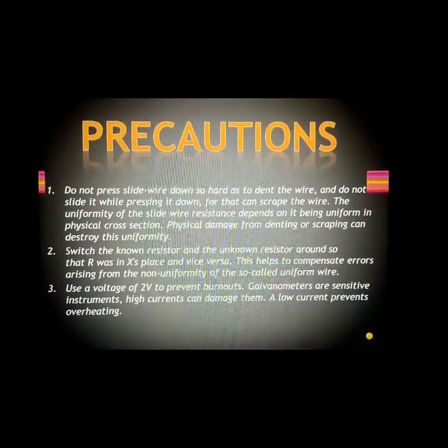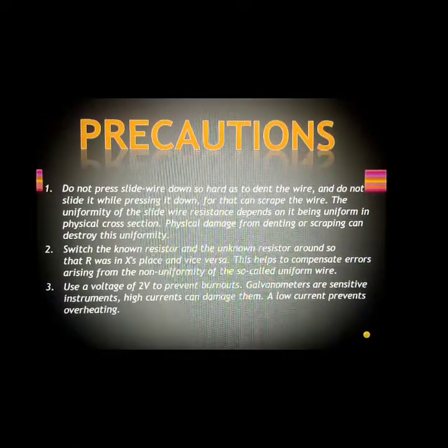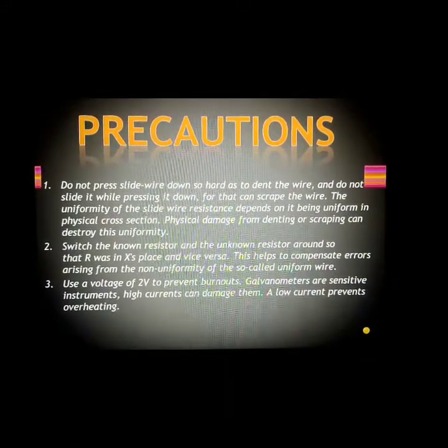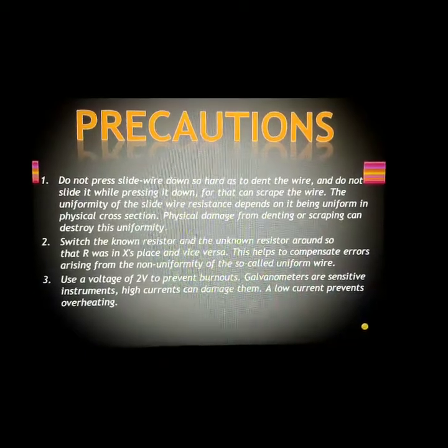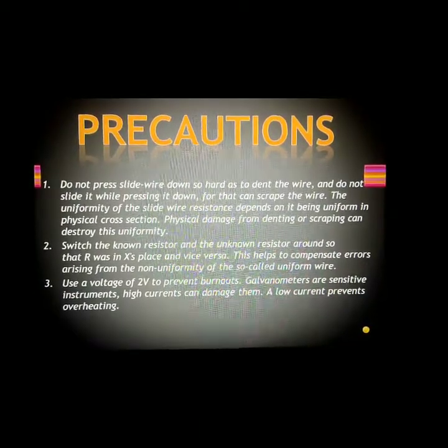Use a voltage of 2 volts to prevent burnouts. Galvanometers are sensitive instruments. High currents can damage them. A low current prevents overheating as well.